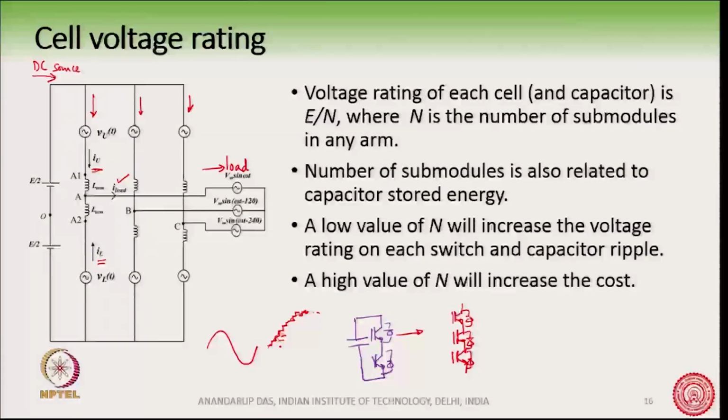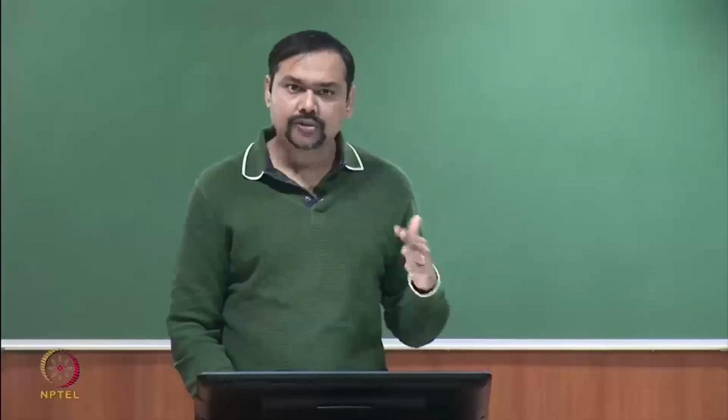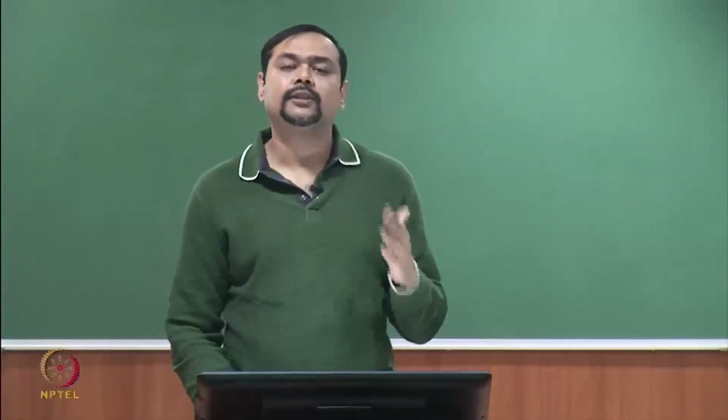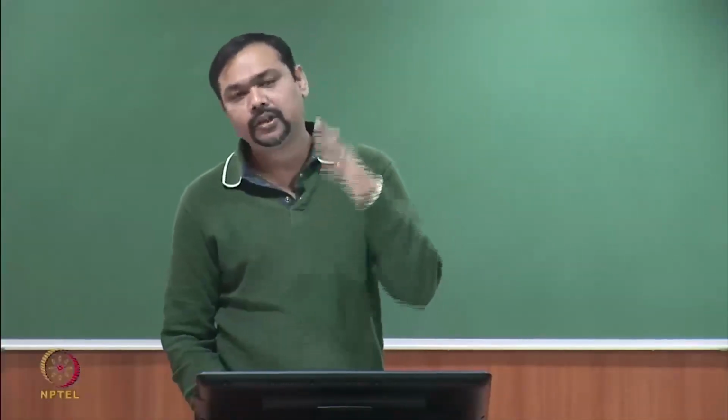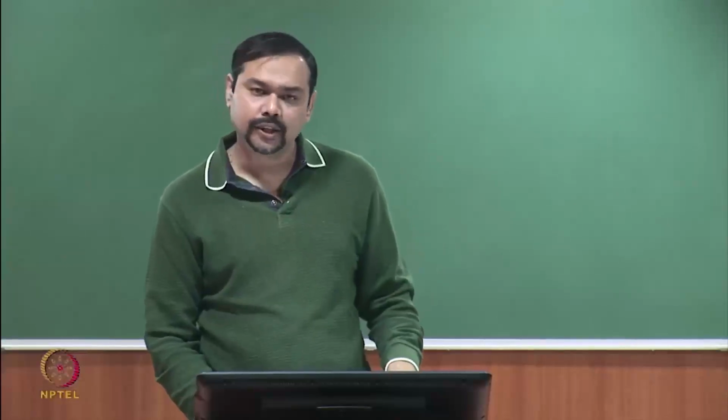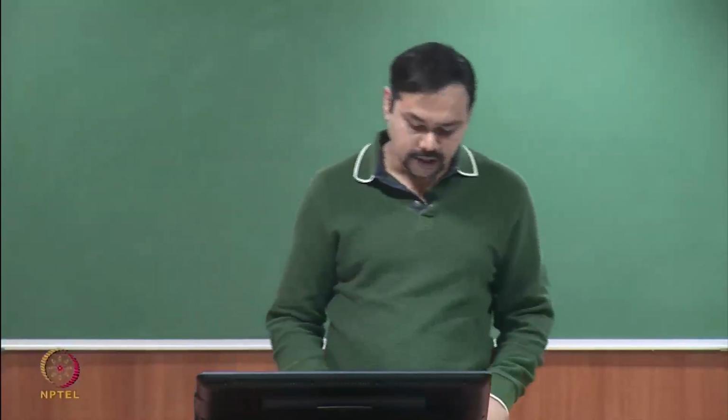So, it is important that the capacitors hold their voltage. Now, when this real power is flowing through the capacitors, they will not be able to hold that voltage, because the energy corresponding to this real power will cause the capacitor voltage to either go up or go down, depending on which direction the energy is flowing, based on the half CV square.